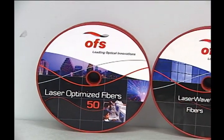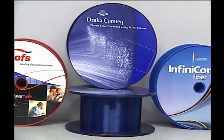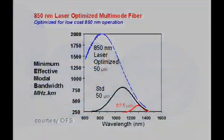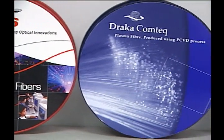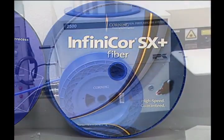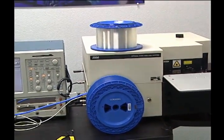This new measurement became called Restricted Mode Launch Bandwidth, or RML bandwidth. With the introduction of the 10 gigabit Ethernet standard in June 2002, a new 50 micron fiber was introduced with a 2,000 megahertz per kilometer EMB, or roughly 10 times the bandwidth of legacy 62.5 micron fiber performance. This fiber was called Laser Optimized 50 Micron Multimode Fiber. Since VCSELs have a much smaller spot size than LEDs, and since gigabit Ethernet operational distances are limited by bandwidth, the higher bandwidth 50 micron fibers have become the preferred choice.